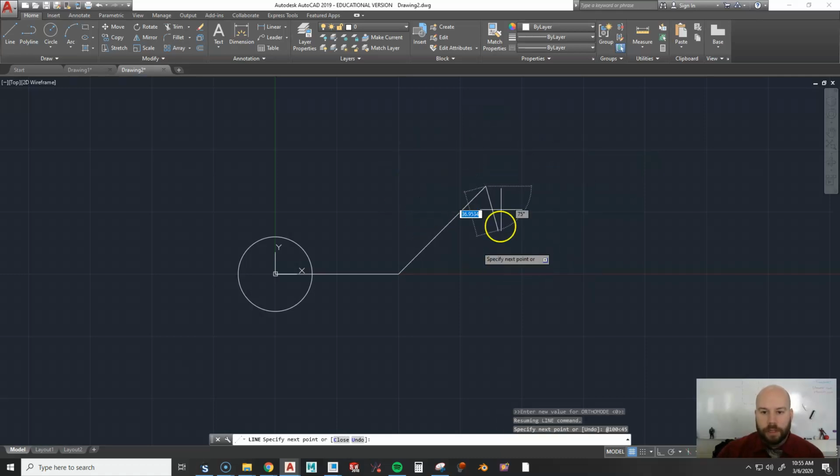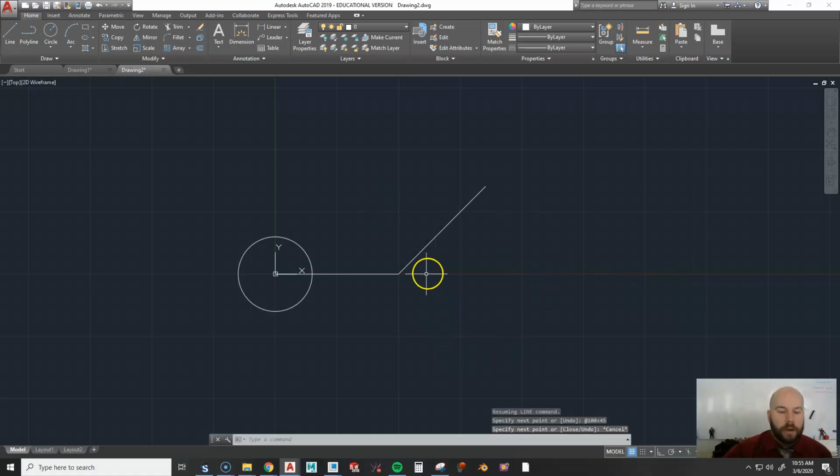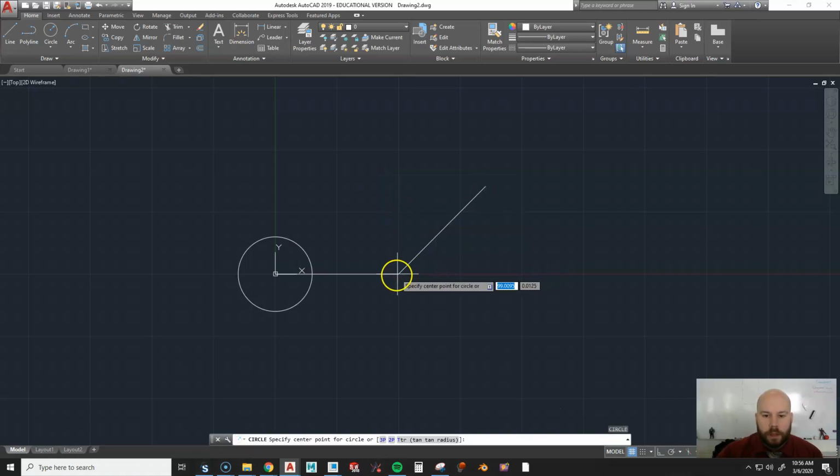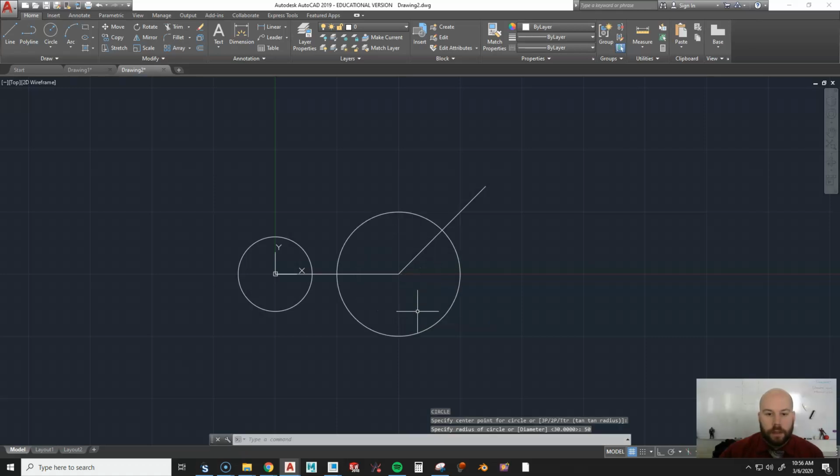And now that brings me to my next spot. Okay, so now I'm going to hit escape, get out of here, and start putting in those other circles. So I'm going to go C, enter. This circle here says it has a 50 millimeter radius. I'm going to hit spacebar to go back into circle. I'm going to click. This one has a diameter of 50, so I'm going to say it's a radius of 25. And now I have my 3 locations for my circles.